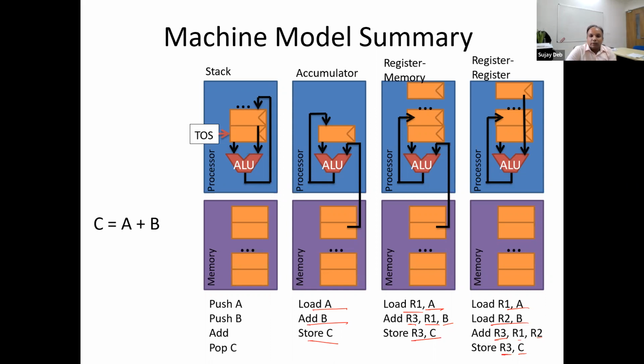Because with registers, if you have, let's say, 16 general purpose registers, you have to have an addressing mechanism to address those registers, to find out what is stored there and so on. So more hardware is needed, but of course it's more efficient than the other models. And most of the processor ISAs you will encounter use this register model if you are dealing with general purpose processors. Okay, so RISC-V, ARM, MIPS, all of them use the register model.